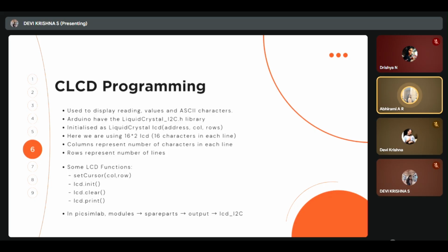In our automation system, we need a simple display to show sensor data. Using a 16x2 LCD gives us two lines of text, 16 characters each, enough for key information without complex graphics. We can use an I2C module because the wiring is minimal, just SDA, SCL, power, and ground. And the control is much simpler than a full parallel interface.